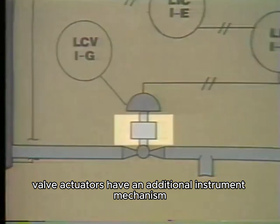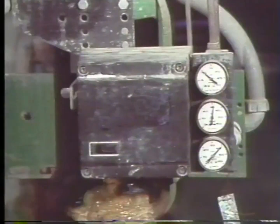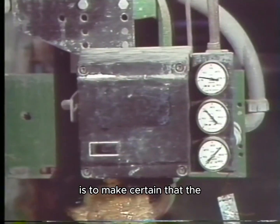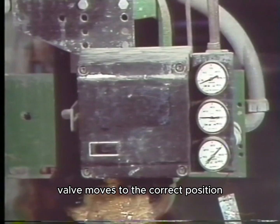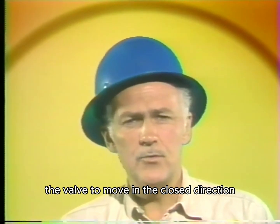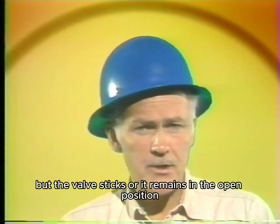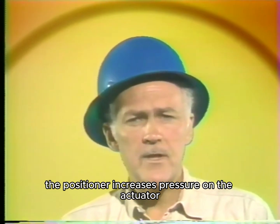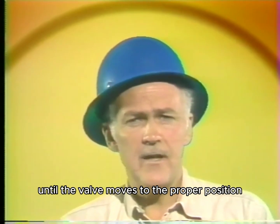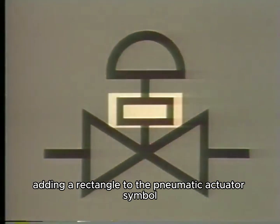Commonly, valve actuators have an additional instrument mechanism referred to as a valve positioner. The function of a valve positioner is to make certain that the valve moves to the correct position dictated by the controller. For example, if the signal from the controller tells the valve to move in the closed direction, but the valve sticks, or it remains in the open position, the positioner increases pressure on the actuator until the valve moves to the proper position. Valves with positioners are symbolized by adding a rectangle to the pneumatic actuator symbol.